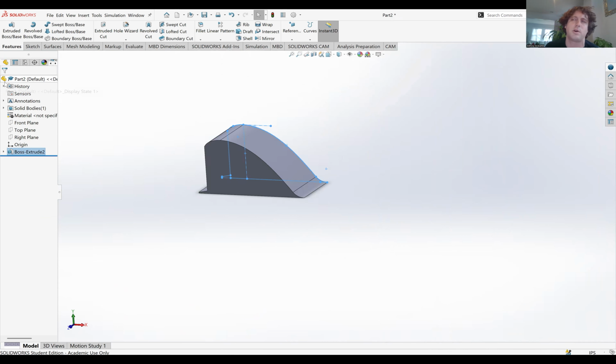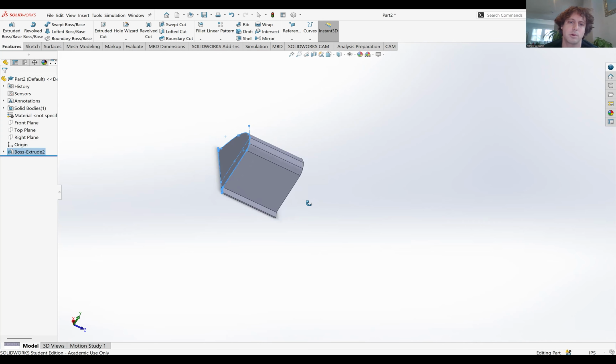I gave you a channel width of 0.11 meters, which is 110 millimeters. But in actuality, the channel has a little bit of a taper, unfortunately, and just to make it easy to stick it in, it's nice to make it a little bit narrower than the channel, and you don't really lose that much flow around the sides, if any at all. We made it 5 millimeters narrower than what I told you, but in actuality, it does get pretty snug towards the bottom. So that should be good.